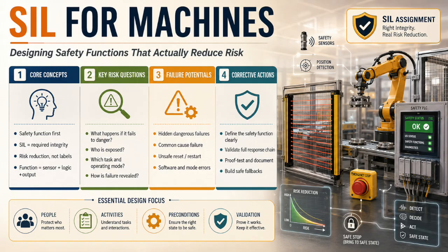So if your machine safety argument depends heavily on emergency stop use, you need to challenge the design. And if operators are using the emergency stop as a routine production stop, that is not just a behavior issue. That is a design signal. It means the machine may need better operational stop controls, better HMI design, better sequencing, better hold-to-run logic, better access modes, or better fault recovery. Do not hide routine control needs inside emergency stop design. That is how safety functions get misused.